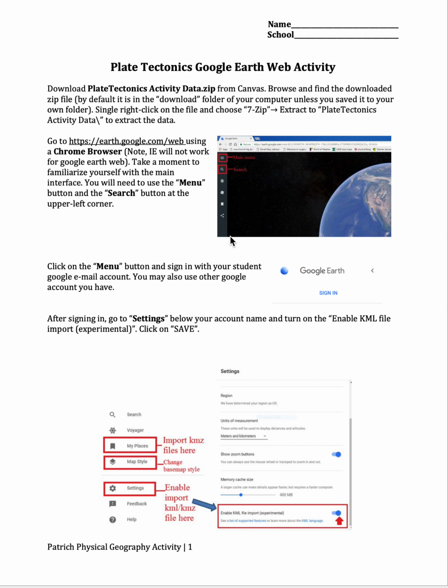Again, where you found this PDF, right next to it is where you'll find the file that you'll download, the KML file. Then you'll have to upload the file. Click on Save and upload it to this account. It will then layer as an image on top of the entire Earth. It's going to project essentially a couple different things. It's going to identify fault boundaries and zones, and it's going to show you divergence and the age in which that rock was deposited. So it's really a neat activity.